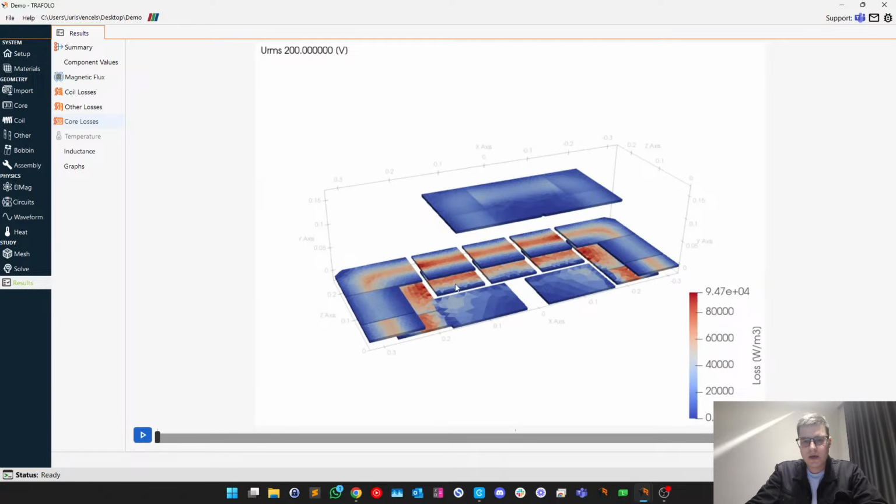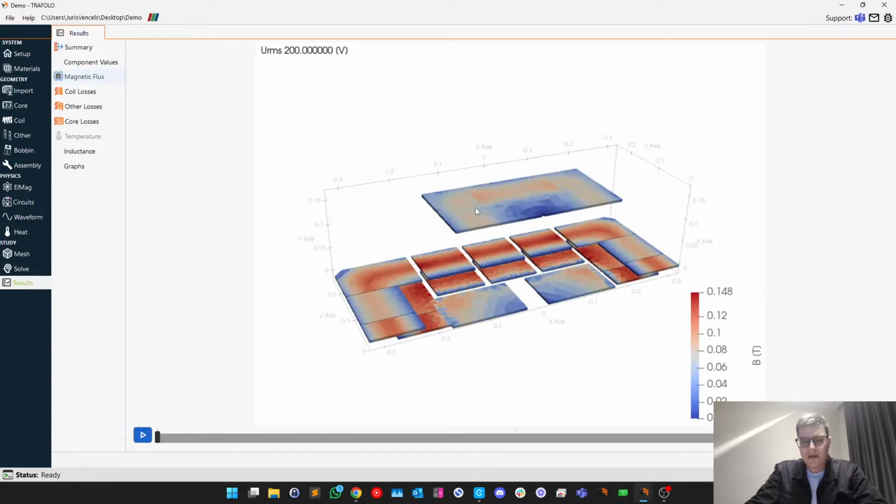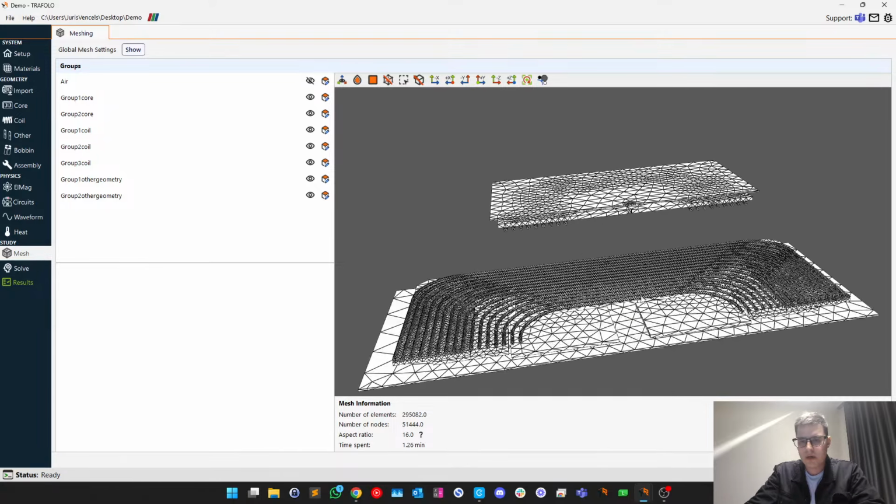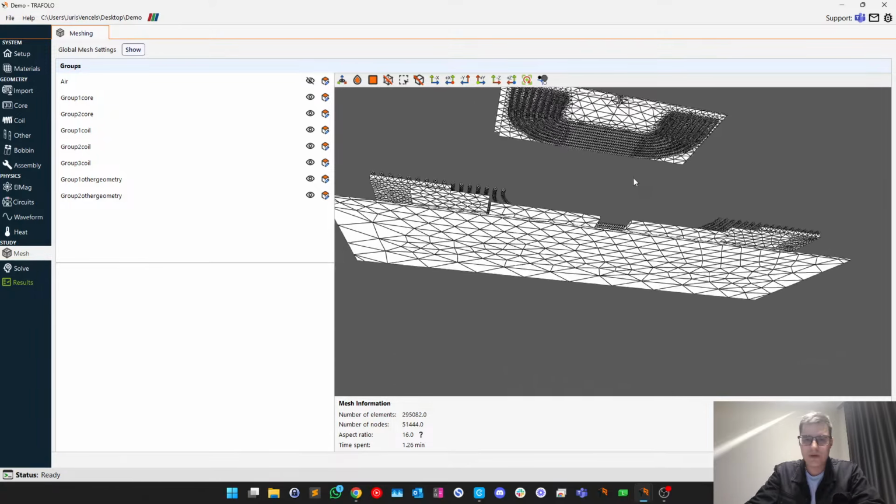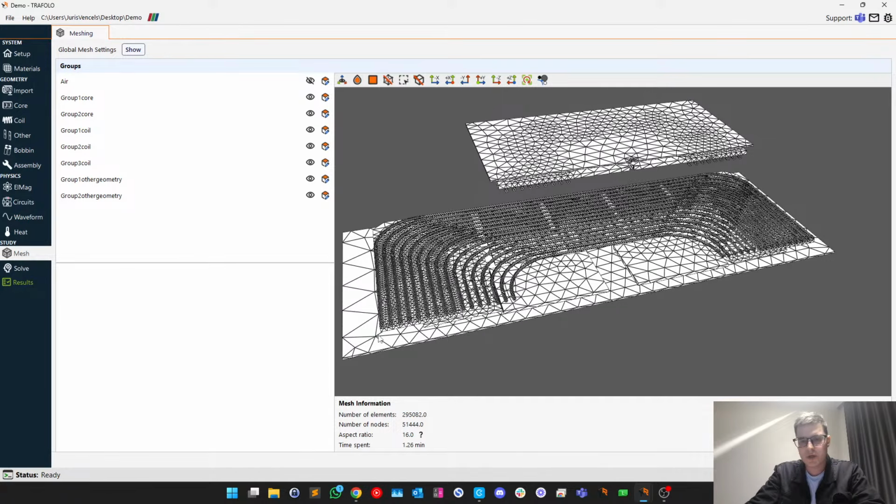Also, as you can see, the magnetic flux is here. So both primary and secondary coils generate enough flux and are coupled good enough so that this receiver coil also receives some flux. If there would be no resonance, you would almost see no magnetic flux in this core section. So very simple, very beautiful template. So now you can start playing with wireless power transfer yourself.